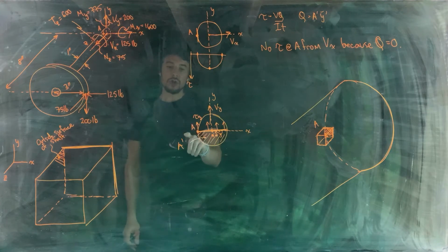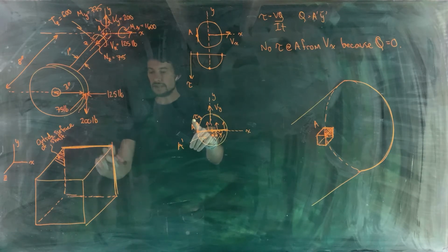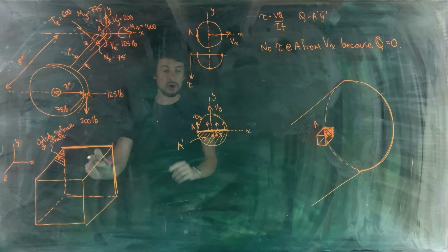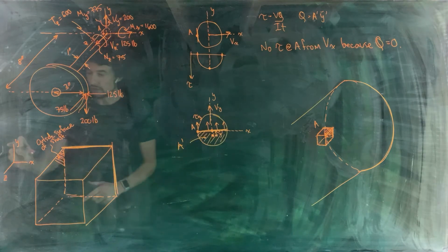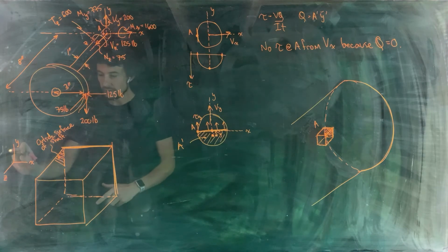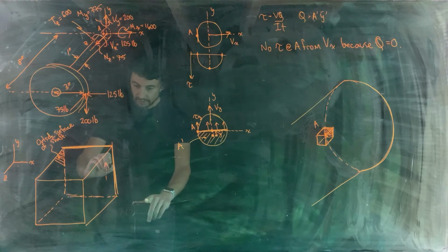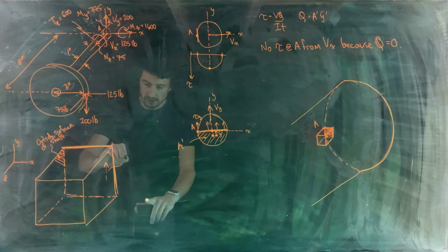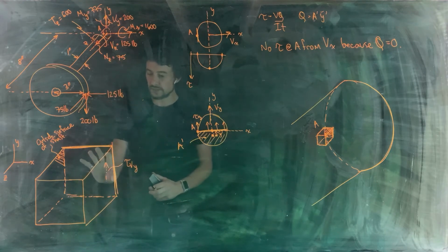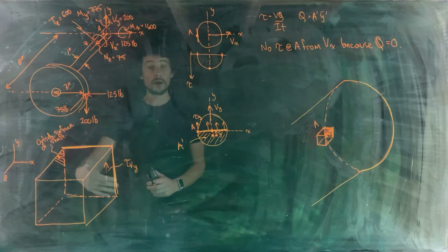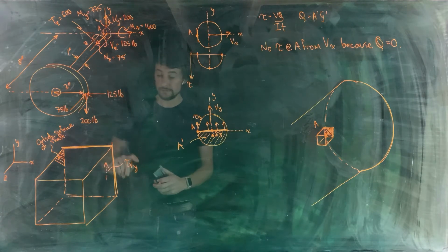Okay. So what we want to do is place a shear stress on the face of the element that's in the section plane of A, so the back face. And to do that, all we need to do is draw a shear stress on that face that is in the positive y direction. So this is why you want to have these axes right here, because looking at this, you can place a shear stress on this back face that is in the positive y direction, and this is tau Vy. Remember that whenever you're placing shear stresses on a volumetric element, they're always parallel to the face of the element that you're positioning them on. Normal stresses are always perpendicular to the face of the element.